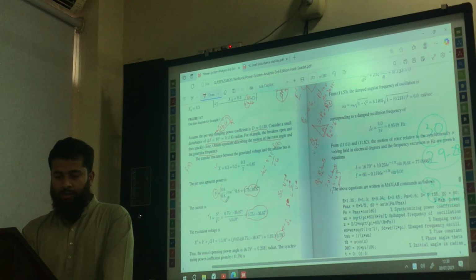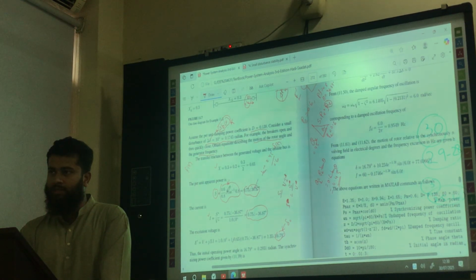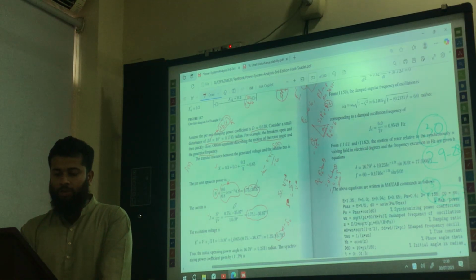The book here, the author has done it in another way. Okay, it will be difficult for you to understand this thing. You can just follow this power triangle form, and you can easily find the same thing for S. Now this is your S. So what will be the S conjugate? Simply put a minus sign in the angle.